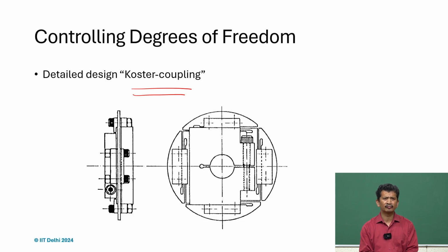Many of these materials are from Philips, and ASML is also a spin-off of Philips. If you look at those machines, all these elements are everywhere. In any precision machine, the flexure elements, the degrees of freedom, and this kind of coupling will be embedded. After this course, you will be able to understand and appreciate why these small holes, slits and cuts are provided, and how this flexibility gives a good solution to address the problems related to over constraints, and gives very cost effective solutions using these methods.